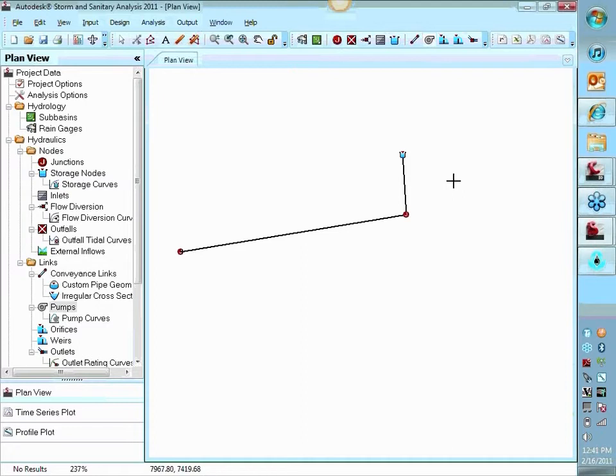After that, we need to connect a pump. So a pump, you can see this little spacer here in between. These are all links on this side. So these are lines, the links of the lines. The structures, these are all nodes. To connect links, I have to have a downstream structure, so I do have to place another junction here. And then I can connect this pump in between.